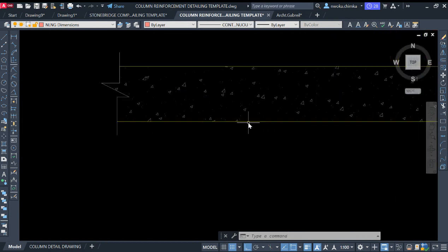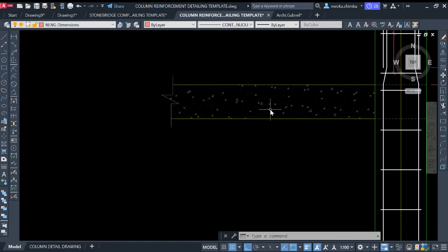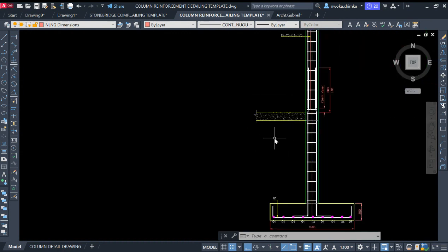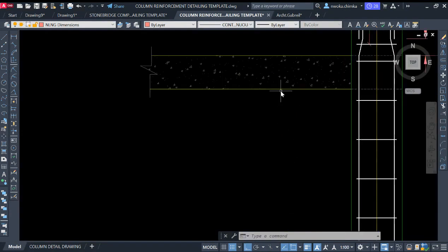So next thing again is to offset our layer, damp-proof course, and know that there are some layers under this slab because this slab will not directly sit on the soil, because here there will be soil at this place. So first of all, we offset our layers first.